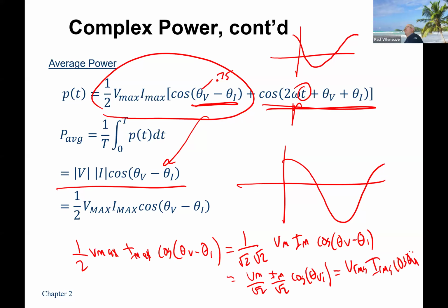That's why. So that whole thing that we called RMS was just a mathematical calculation. For us, it's just a nice, convenient way to distribute that 1/2. Our work requires us to have a 1/2. But in actuality, we can distribute it and just call them RMS terms. So why do we convert to RMS? Just to make the power equation work. We're looking for the average power over one sine wave, and if we use the peak values, it's not going to give us the calculations we need. But if we use the RMS values, our results work out. So the use of the term RMS is just a simplification to say divide by the square root of 2.